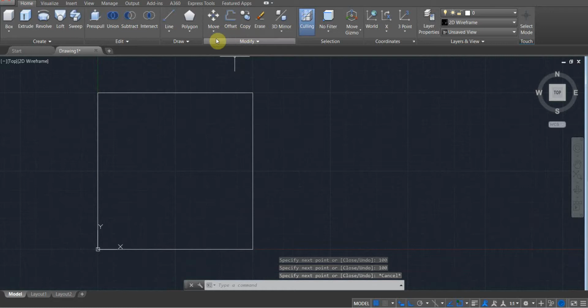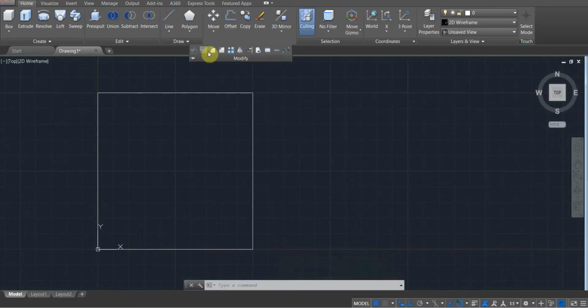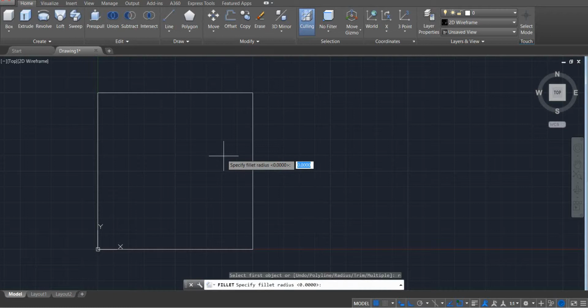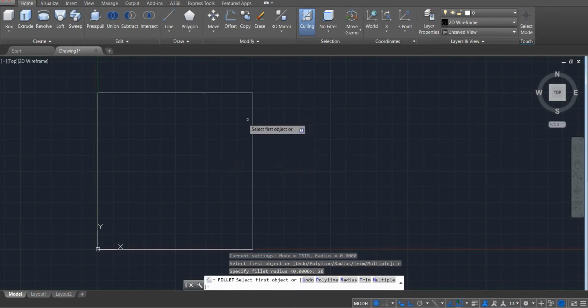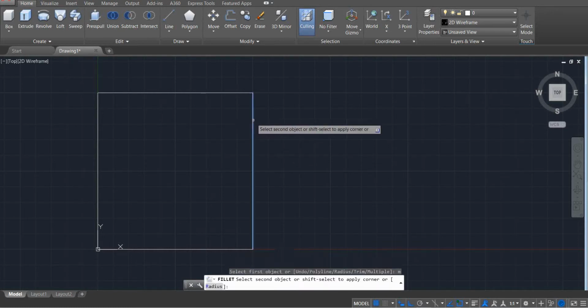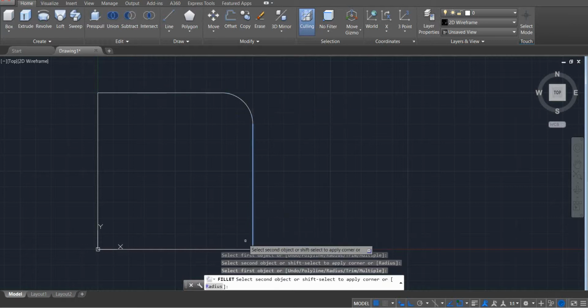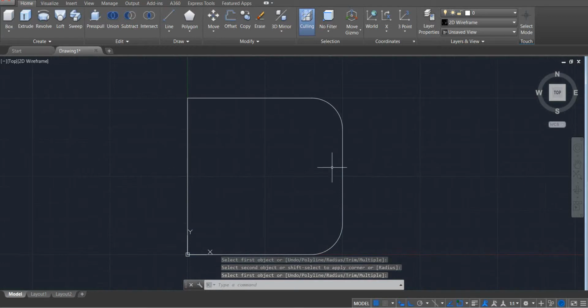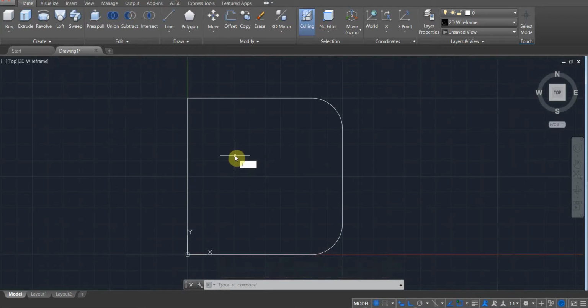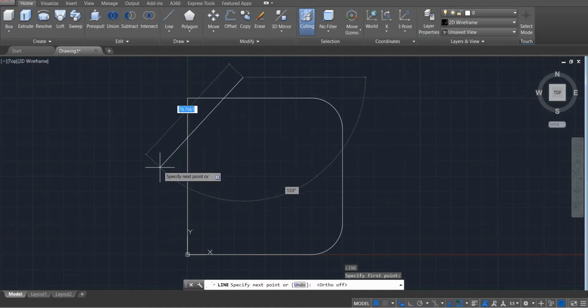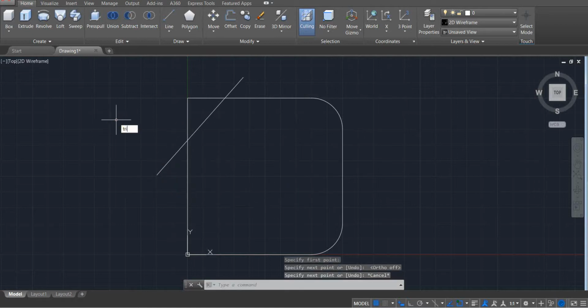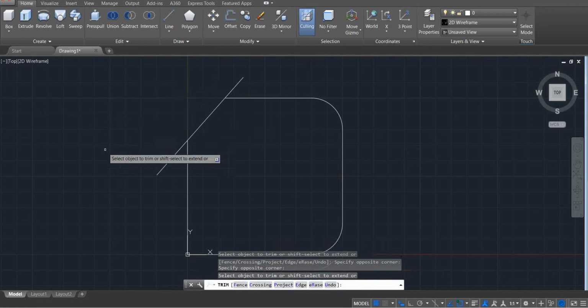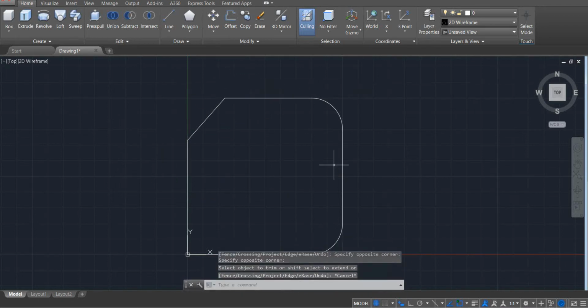Let us even apply the fillet command, and I'm gonna specify the radius of the fillet, let's say 20 at this corner, and it's gonna be multiple at these corners in this way, like I'm applying this fillet at these two corners, and press enter. So this is simply a 2-dimensional sketch. Whatever it is, we can add more complication, like I'm gonna draw a line, for example, from this point. F8 just deactivated. Then I'm gonna use the trim command to trim the shape in this way. So how about if we have this 2-dimensional sketch?